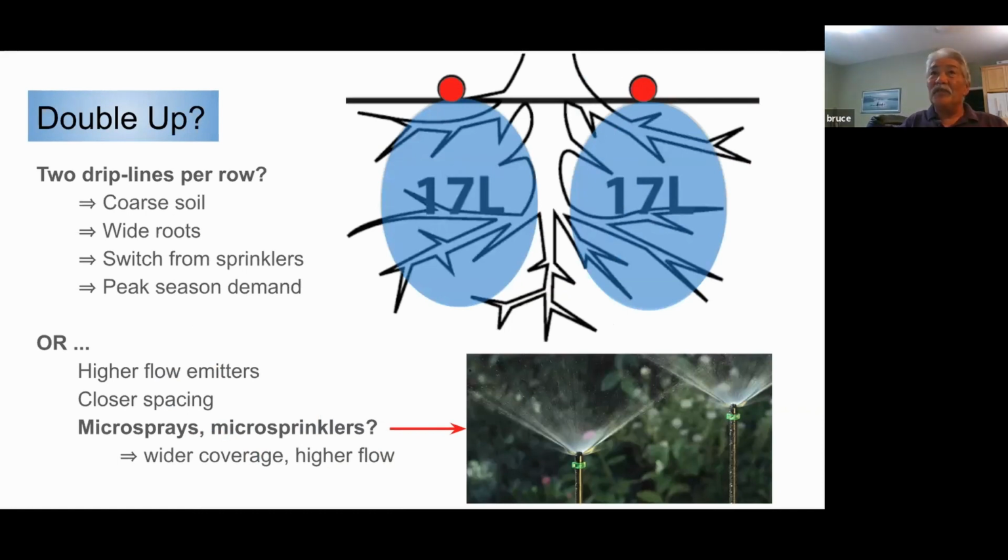One tactic that's been used a lot with drip irrigation, and we've talked about this, is that if you have a single row of drip irrigation and you're not satisfied with the results, in a lot of circumstances, we've done this in cherries and in blueberries, you'll go to 2 rows, one on either opposite side of the trees. On a brand new tree, they may start out with 1 row, and then as the tree matures, they'll add the 2nd row of drip on the other side.